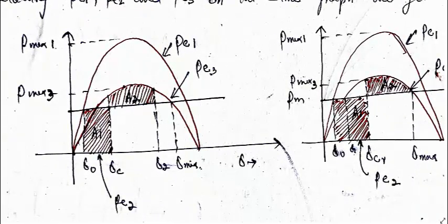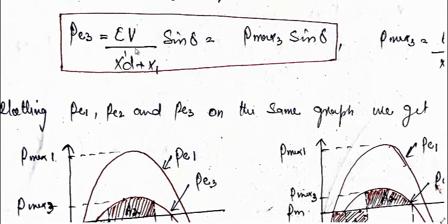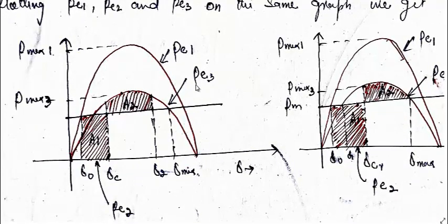Now this is the accelerating area. At this point the fault has cleared and Pe has been restored to Pe3, because line 1 has been opened. So Pe will be restored to Pe3. Some power is supplied through line 1. Now the electrical power will follow this curve. So for a stable system, it will follow this curve and area 1 will be equal to area 2. In the general case, when we have some area available apart from this A2, this area 2 will be equal to area 1 and the system will be stable.